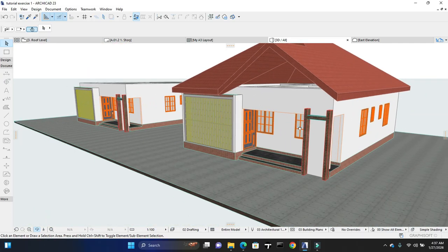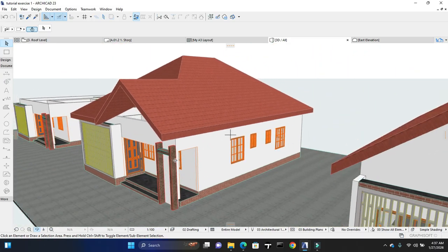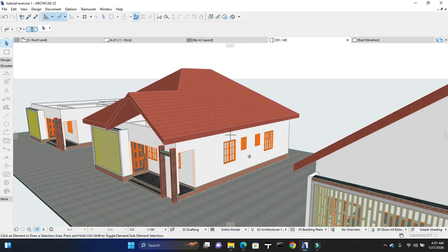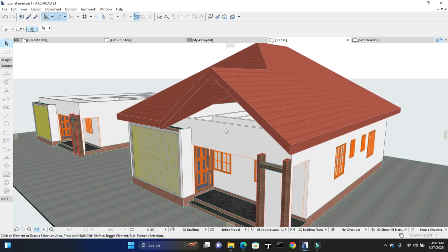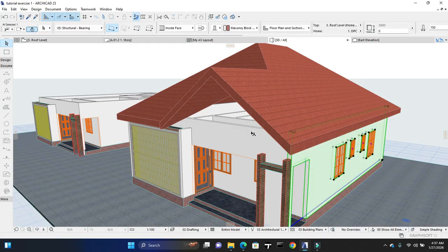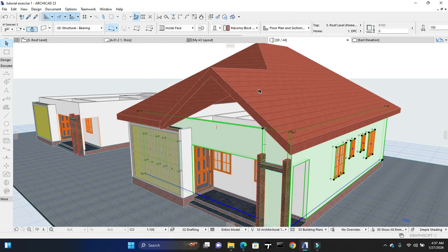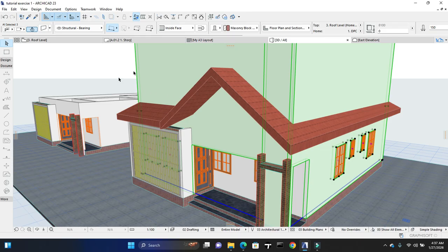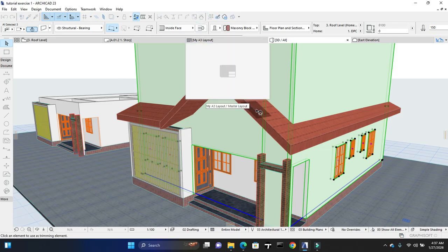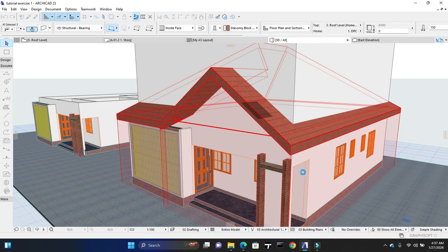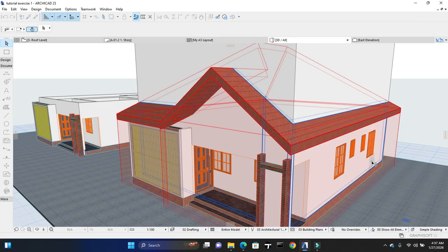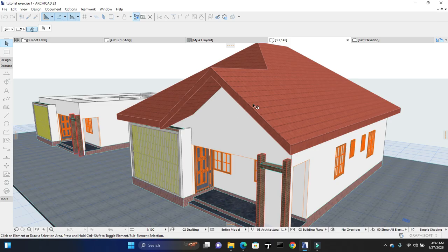Now, as you can see, clean gable and hip combination. You see that this hip is coming out here, so you can simply reduce it to align at that point. So if you go to your roof plan, when you want to do that, instead of reducing it from here, you can't. You have to reduce it from here. So with that selected, you just click and take it back, and then when you go back, you see, that's how clean it is.